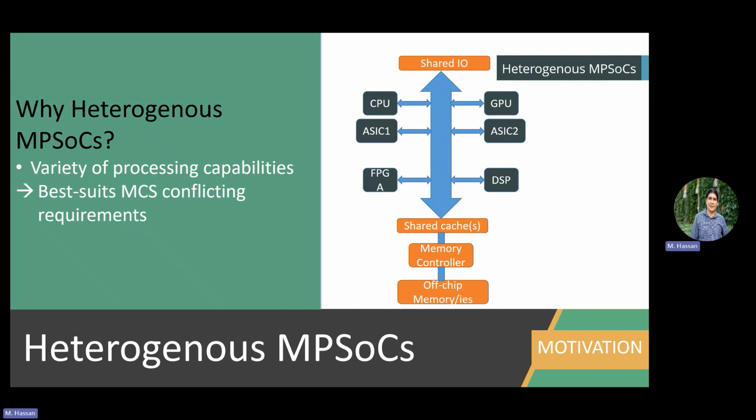So if you share the communication channel, then the critical task on the CPU is in fact susceptible to attack, to interference, to contention from the non-critical task, right? You see the problem is that now you are deploying both critical and non-critical tasks on the same SoC, which means the critical tasks, in fact, are impacted by the non-critical ones, right? Most of the challenges we will see later on come from this sharing of resources, right?